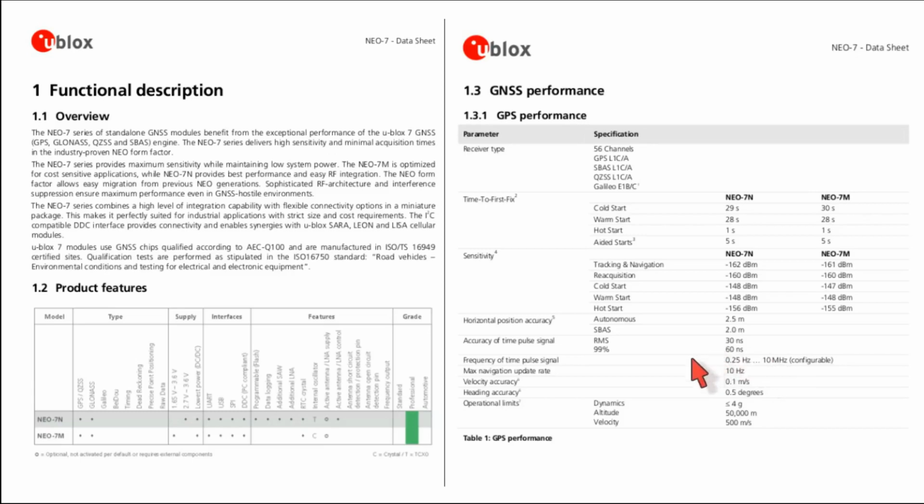On the accuracy of the PPS, the root mean square is 30 nanoseconds, and in 99% of the cases it's at least 60 nanoseconds. At 10 MHz, one period is 100 nanoseconds long, and at 50% duty cycle, a pulse is 50 nanoseconds wide. We may be missing or getting one extra pulse in 10 million, which is pretty good.